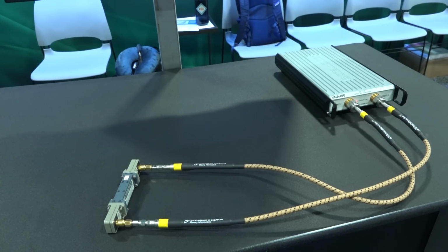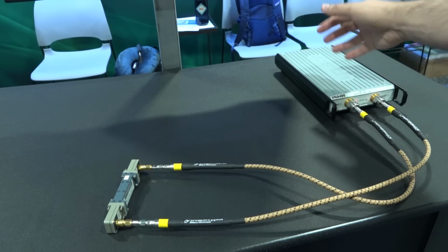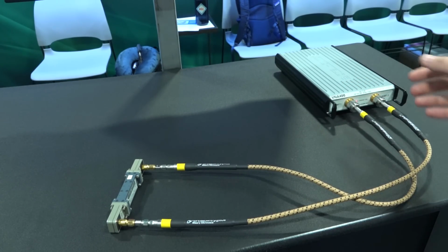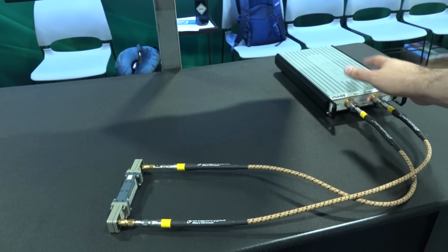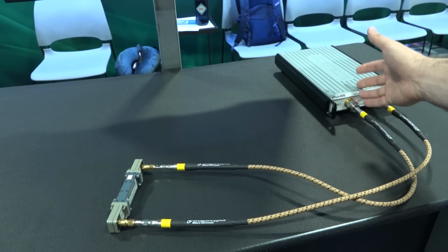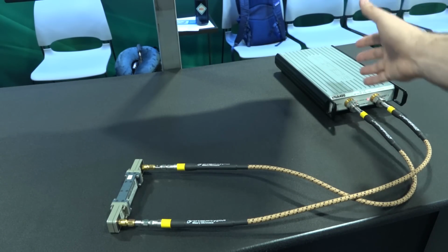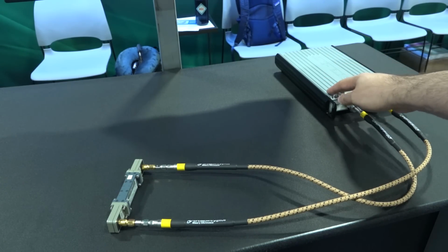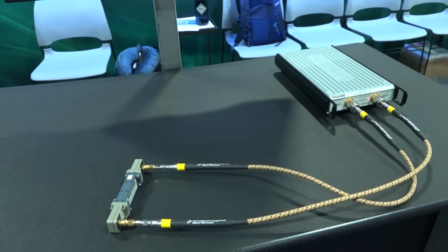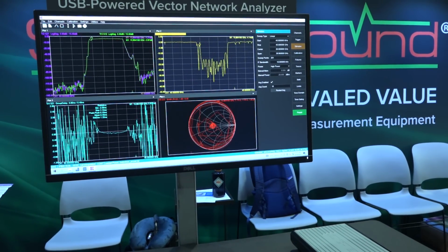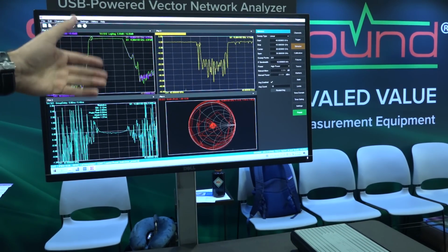And we also now have a brand new VNA 400, which is a 40 gigahertz two-port network analyzer that Siglent has also released. This is a purely USB-powered unit, under 15 watts, just connected with the USB in the back, which makes it a lot easier to use in the field. You can just plug it into the computer and it'll be ready to go. We're looking at about minus 135 dB of dynamic range in the low frequency, minus 120 dB of dynamic range in the higher frequency. And the software is written with the same fast-paced GUI interface that you see.